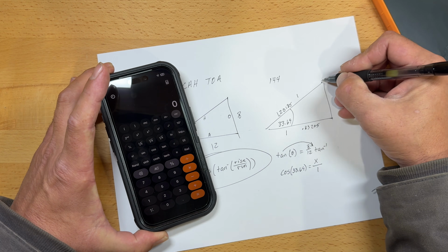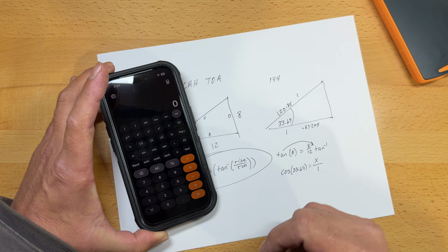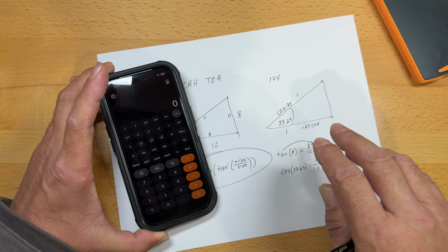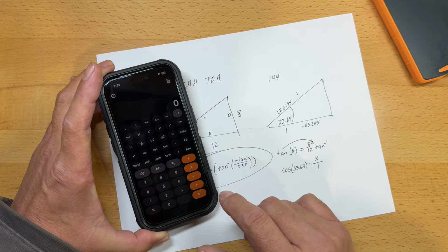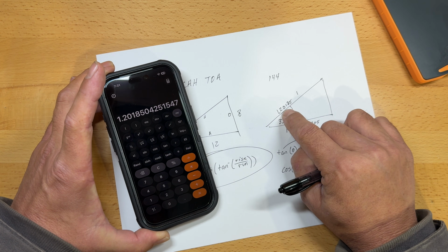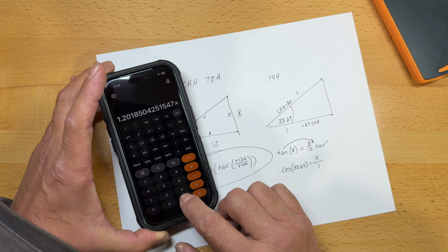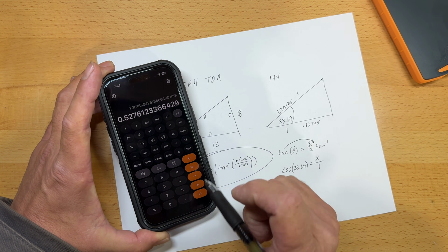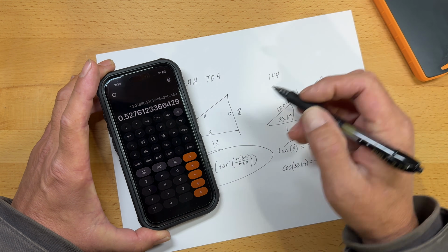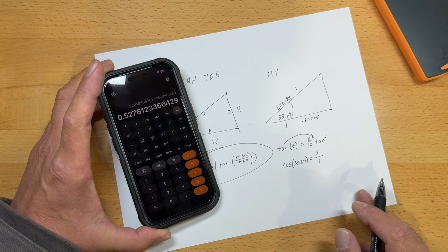Now if we multiply it by that 0.439, that'll tell us for this particular pitch how much longer, excuse me, how much longer our first jack rafter needs to be in comparison to what the construction calculator is showing us. So we take the multiplier, which was 1.20185, and multiply that by 0.439, and that tells us that the first jack rafter actually needs to be a little over a ½ inch longer than what the construction calculator was showing us.